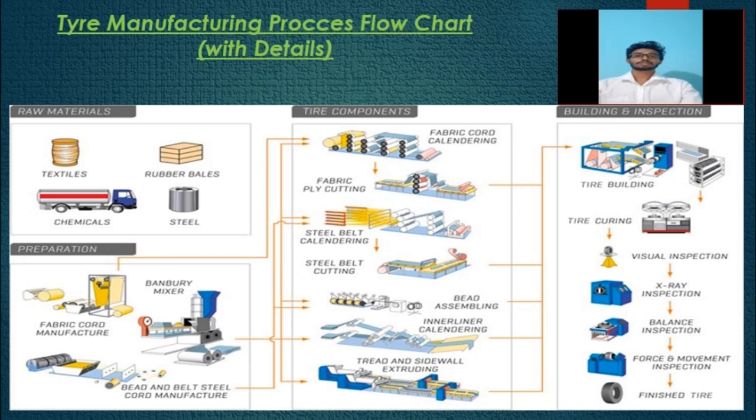This process brings together everything: the body plies, belts, inner liner, tread, and sidewall sections. For a radial tire, it's a two-step process on a flat drum. First, the inner liner wraps around the drum, followed by the body plies and bead assemblies. Then the drum inflates, making a piece turn up and cover the bead. Sidewall sections are added next. In the second step, other machines add belts, a nylon cap, and the tread, but the tire isn't done yet.